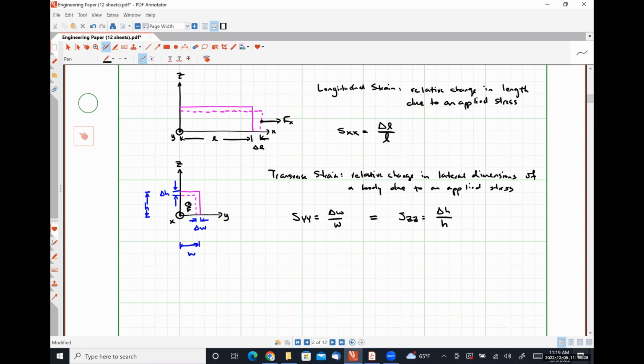So if we have some original volume, the volume times the density gives us our mass, right? If we stretch the beam, does the mass change? Of course not, right? We're not creating or destroying anything, we're just changing its shape. So effectively, we have to experience all three of these strains, because if we change in one dimension, the other dimensions have to change in order to maintain constant mass for our beam, all right? It's as simple as that, simple logic there, okay.